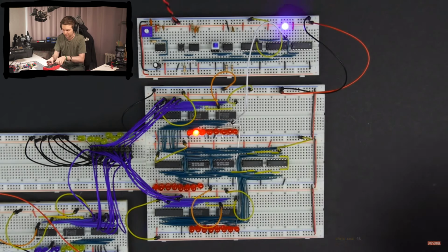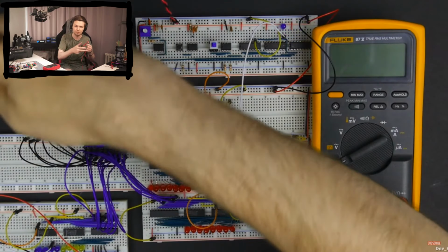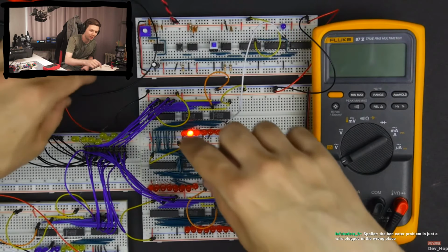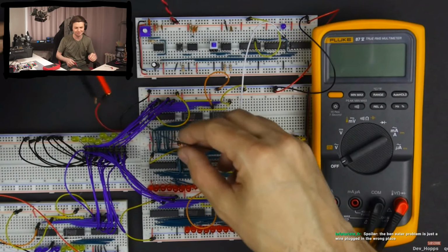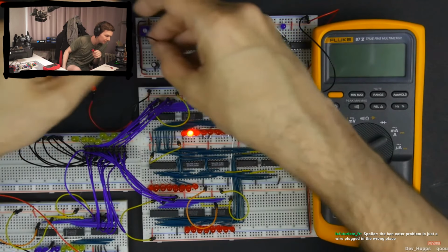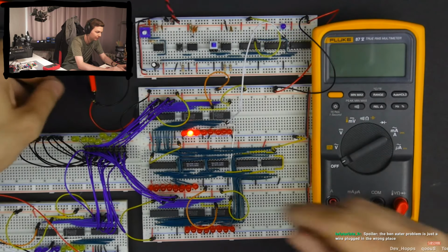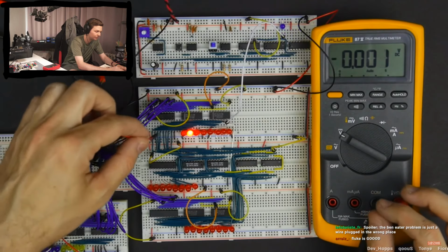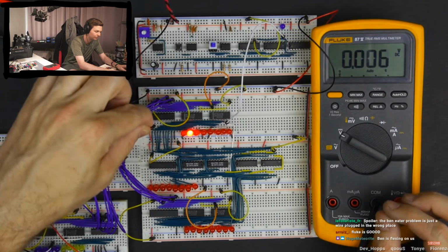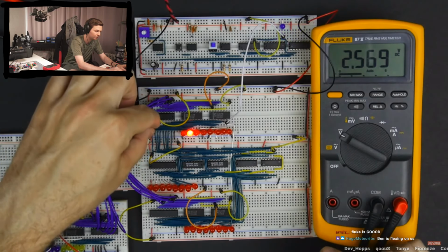And actually, I'm going to get a multimeter over here. Yeah, as nice as it is having all these LEDs everywhere, sometimes just measuring voltages can be really helpful. So I've got a Fluke multimeter here, and then the probes are just these little clip probes that I have these wires attached to. So I can just hook my ground over here somewhere, and then I can probe around with this and see what we've got. So go over here to volts. And so the LED should be connected to this pin here. And yeah, we're seeing some voltage there.